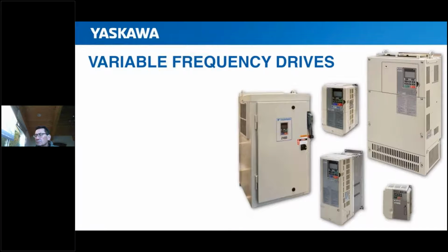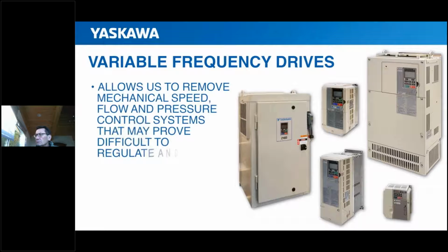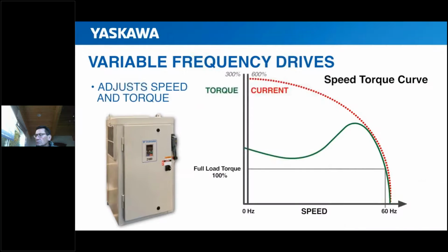Using a variable frequency drive for these types of industrial and commercial applications allows us to remove mechanical speed, flow, and pressure control systems that may prove difficult to regulate and could possibly be failure points. Instead, the drive easily adjusts speed and torque to given system demands.